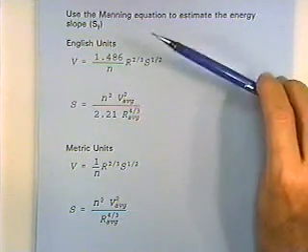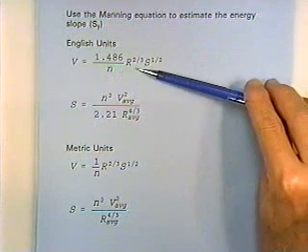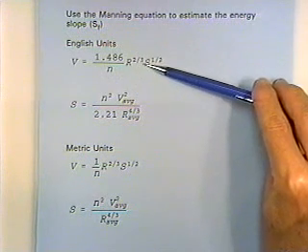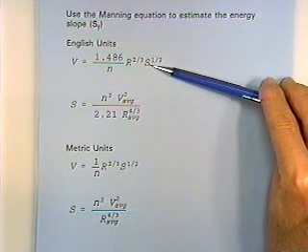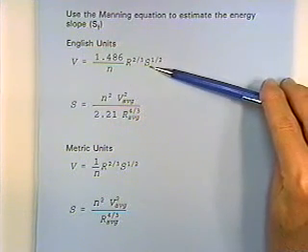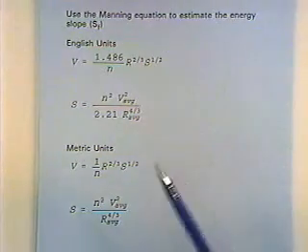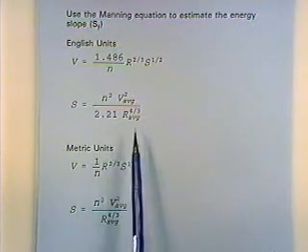Manning's equation has velocity equal to 1.486 times the roughness coefficient times the hydraulic radius to the 2/3 times S to the 1/2. Now that's the slope of everything. That's the slope of the energy line, the channel bottom, and the water surface in uniform flow. It's the slope of the energy line now. And so we'll solve for S, and that's the slope of the energy line.